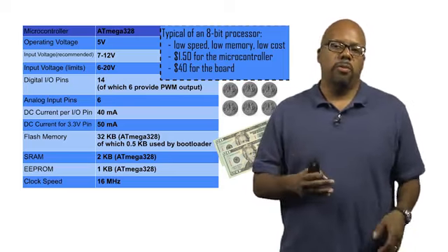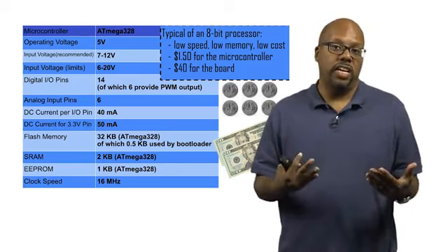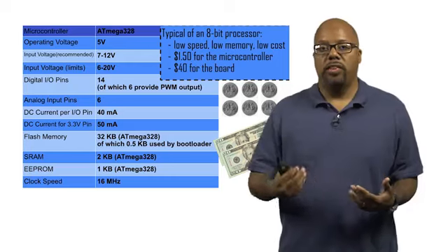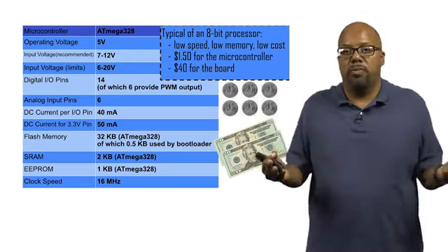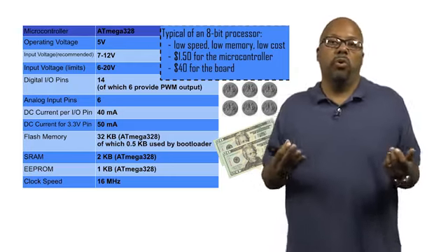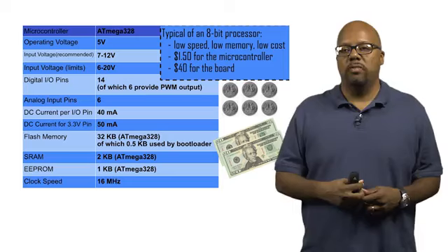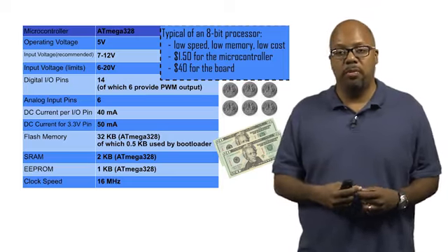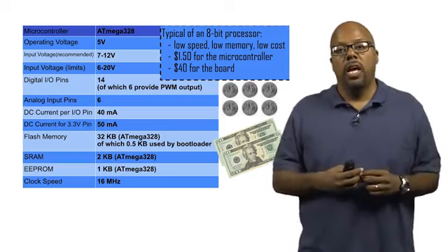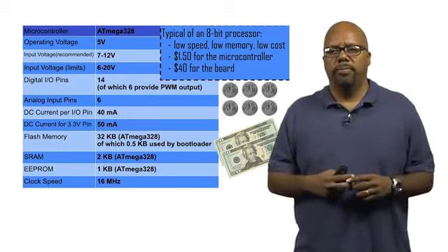Non-volatile memory means that it holds its data even if it loses power. That thumb drive I just showed you is unplugged from power right now, but it's still storing its data. That's what you want for your program. So your programs go into flash memory, and it's only got 32 kilobytes of flash memory, which is not much at all, but it's enough for what we're doing.